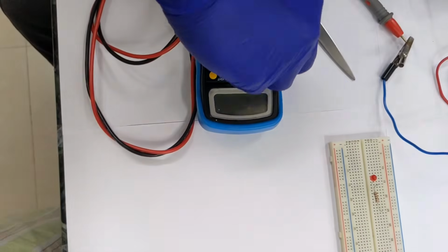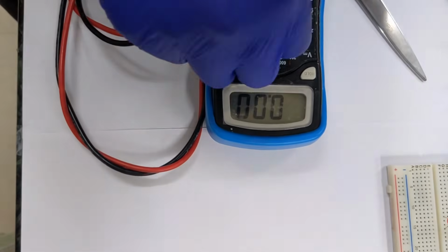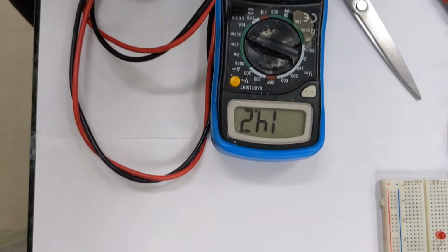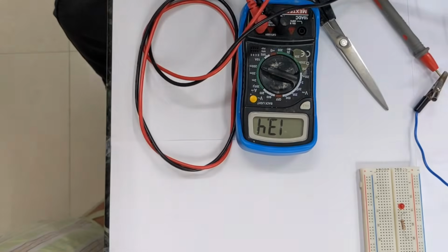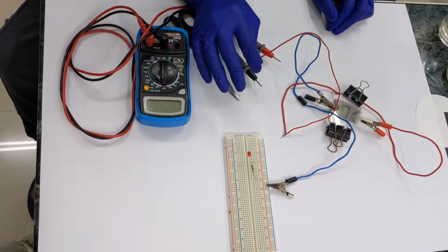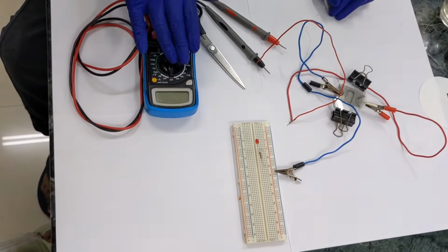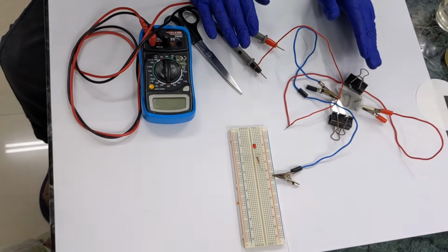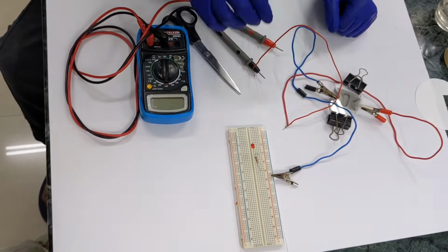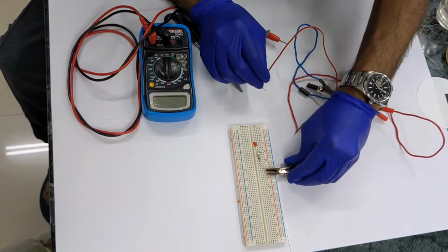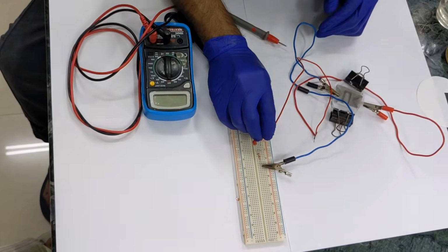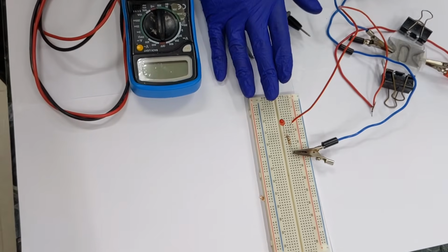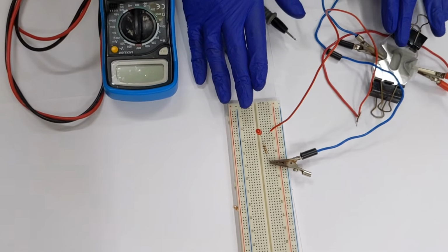Let me check the current. This is how you will measure the current and voltage. Once you have noted the value of voltage of the cell, this is to verify that you have constructed the cell correctly. After that, you need to glow the LED. To glow the LED, you connect the terminals to the LED, and you will notice that the LED doesn't glow. It is because the LED rating is more than the voltage that you are providing by one cell.